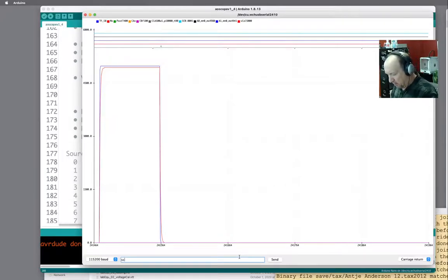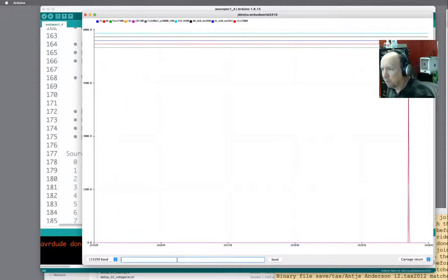So SC100. That's the 10,000 per second divided by 100 equals 100 times per second. Okay. So I did SC100, and up here you can see that we're going to sample once every 10 milliseconds at this point. And then the other thing I want to type is SS for the smooth scroll mode.